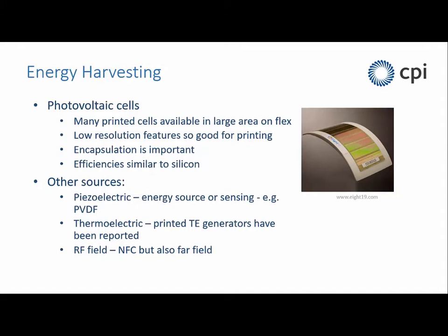And so there are a number of energy harvesting technologies around. Photocells are a common approach. Here's an amorphous silicon device, again ultra thin, about 0.5 millimeters thick. I can curl it round and it still works perfectly well. But these can be attached to labels or to other thin devices and provide significant amount of energy, usually accumulated into something like a rechargeable battery or into a capacitor, so that you can use energy whenever you need it.